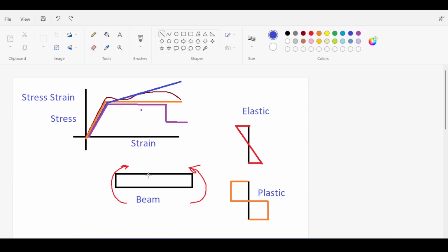So what ends up happening is that the structure actually reaches something called the plastic point, and when the beam section has fully plasticized, then you would have something called the plastic hinge, which means that the plastic hinge is not going to be able to carry any extra moment, or basically will only carry a little extra moment, because it is no longer able to develop any extra stresses, depending on your model. If it's a bilinear, perfectly plastic model, then the stresses don't increase at all. If it's a model with strain hardening, then the stresses might increase.